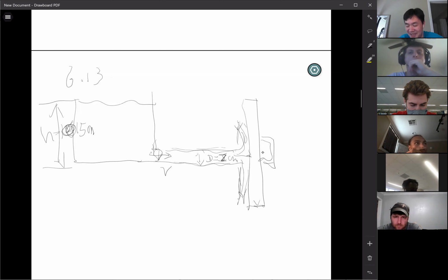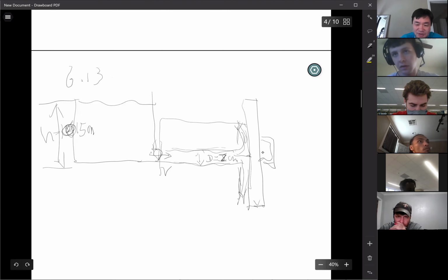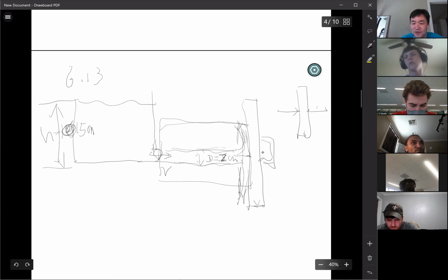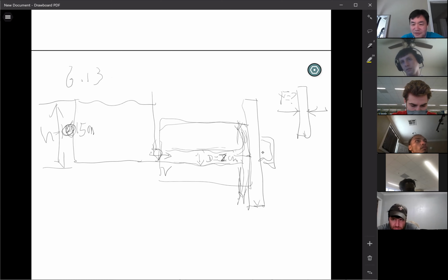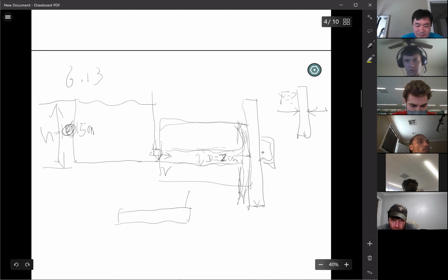Okay, how do you do this? This is conservation of momentum, right? So which one is the target control volume? I think the control volume is this water stream. For the plate, it's easy. You have a force applied to it, you need a force to hold it. Then the question is, what is this force, right? Basically, you want to calculate this force. But actually, the force is coming from the water stream. So you need to draw the free body diagram for the water stream.